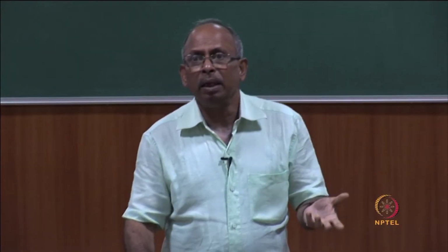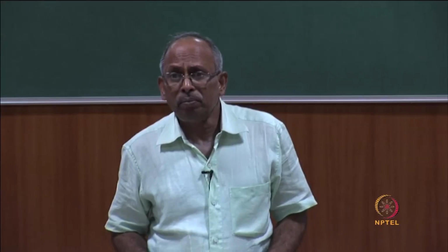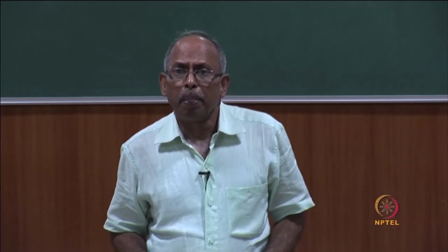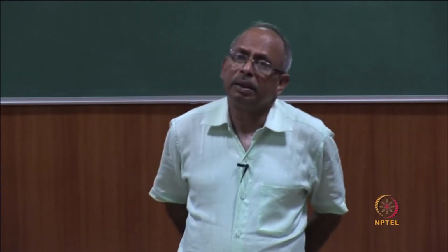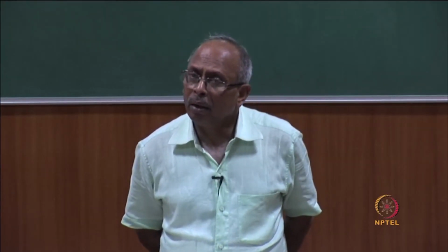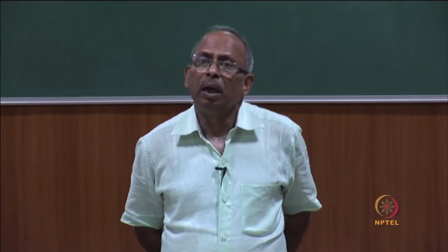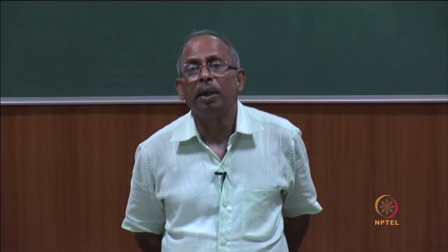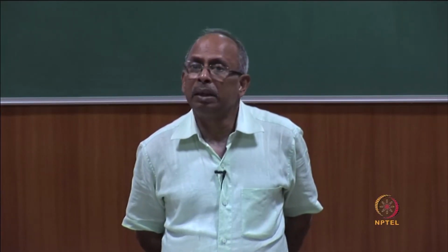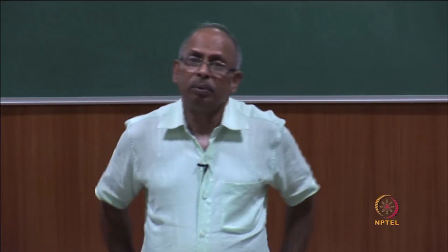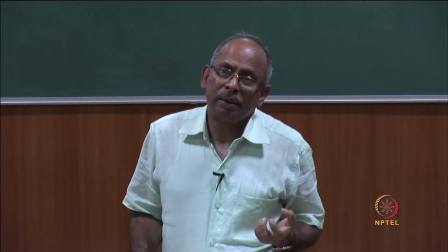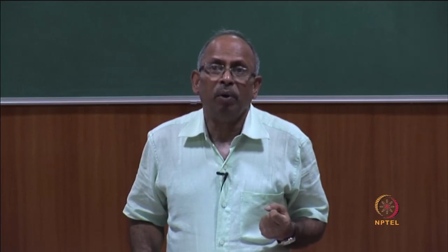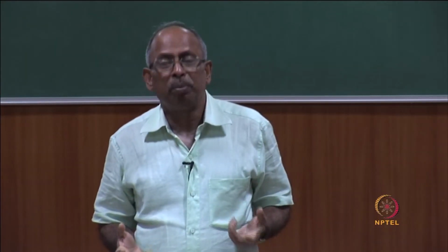So, let us summarize this then. To summarize this, essentially what we have looked into? We have looked into mechanisms of shrinkage today, and we have explained fully how it is related to interlayer movement of interlayer water, and the theories that are available. We have put them forward, and we have understood that it cannot be reversible. But you see this, when you have more than one theory, it is not very easy to come out with a generalized mathematical formulation. So, therefore, you have empirical formulas of prediction of this.